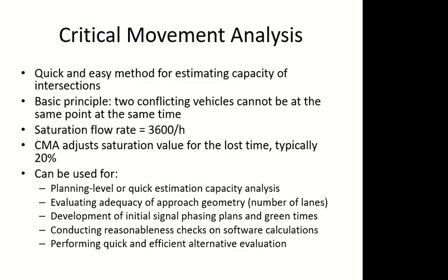So where can we use this critical movement analysis, the quick method? You can use it at the planning stage, not at design stage. Okay, because it's very quick and does not require a lot of data. You can use it if you are comparing between different options. So I cannot do a detailed design for all the options and then compare. So for these options, I will do this quick method to see which option is better, and then I go for the design of that option only. Okay, you can use it for initial timings, initial plans of the signal. Okay, later on that can be improved.